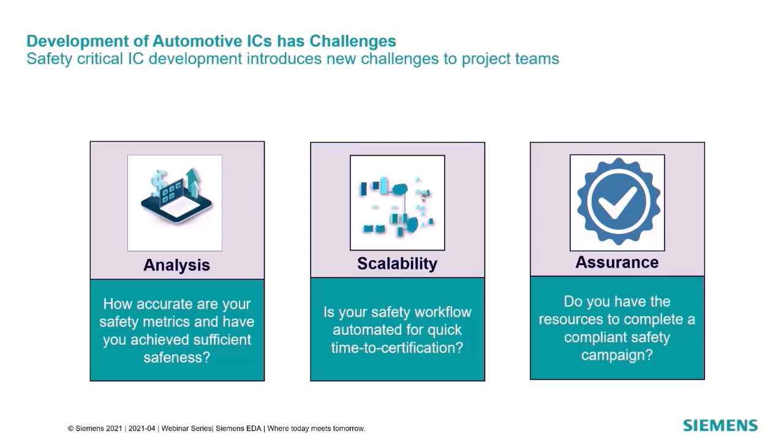But to achieve certification, you need to prove you've complied with the ISO 26262 standard by providing documentation that covers the personnel involved in development and testing, the processes used to develop the solution, and the fault analysis of the product. So as you can see, developing chips for this market is challenging in many ways and takes more time and effort than making chips for non-safety critical markets.